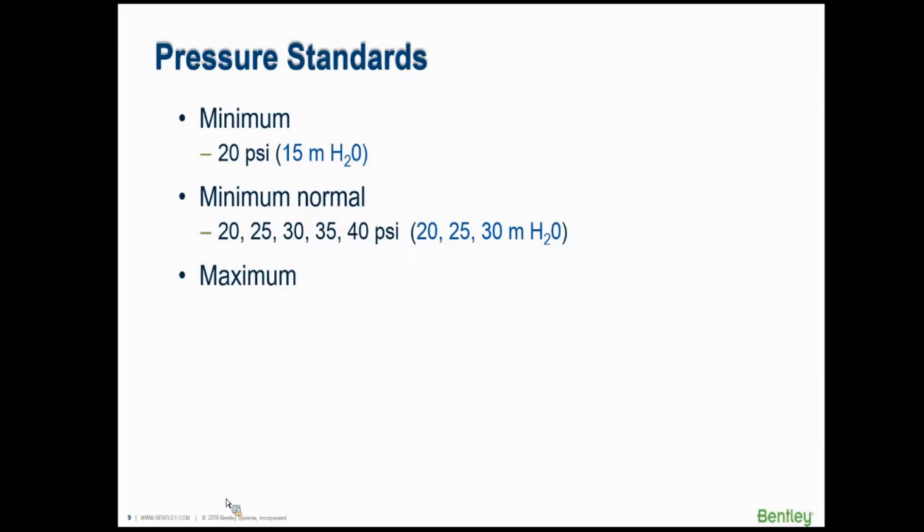What about maximum pressure? What should the maximum be? Well, this is an even less precise number. People will say, oh, we don't want it above 80 PSI, but that's not a reasonable value, because you're going to find places, especially in hilly areas, where the pressures are 100, 125. Usually a more rigorous upper limit might be 150 PSI, because usually that's where water heater blow-offs open up and they start letting water out and popping off these valves on top of water heaters.